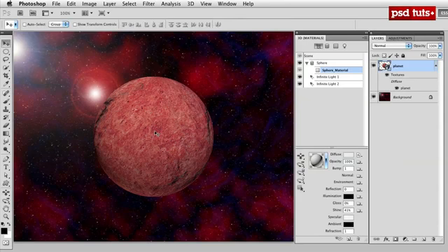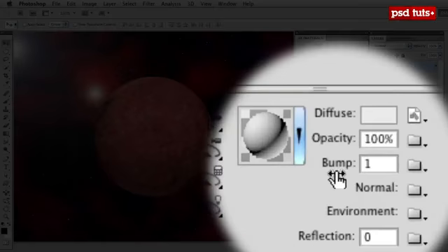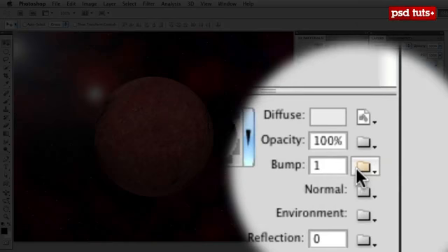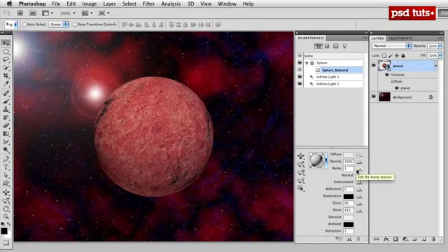This looks pretty good. What I'd like to do though is add even more texture to it, kind of give it some depth. So I want you to see I can also add a bump map. Now a bump map is simply a grayscale image, and in this grayscale image the areas that are white will simply seemingly raise areas in our 3D object, and any area that's black in this grayscale image will make the 3D object appear flat or recessed.